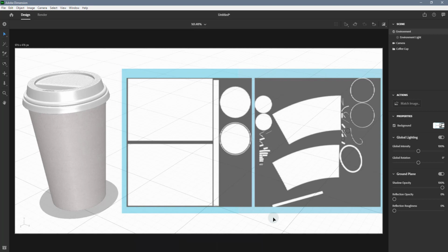Each UV shell has seams that cut the surface so it can be laid flat in UV space. Seams in UV space also mean seams in the textures, which isn't always a bad thing. Logical seams can break the model up for texturing easily. Sometimes seams may not line up between different features of the model in UV space, or may be placed in a way that makes creating a graphic across the seam difficult. Graphic layers in decal mode are projected across seams. You can combine UV export and decals as needed.